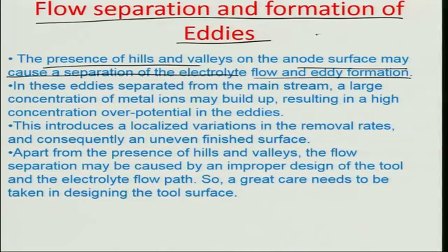So let us say, for example, if the electrolyte from this particular machining zone is flowing ahead, and let me just draw it a little appropriately. This is the machined zone, and let us say these are the regions where such breakdowns are happening. As the electrolyte is flowing here with some small velocity, there is a tendency for recirculating zones, or eddies, to form over these regions.